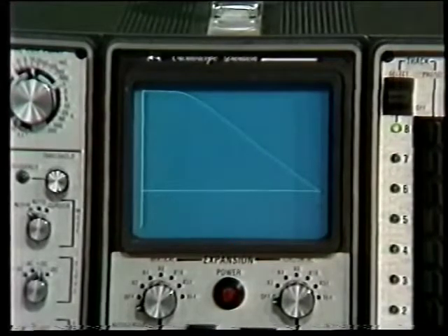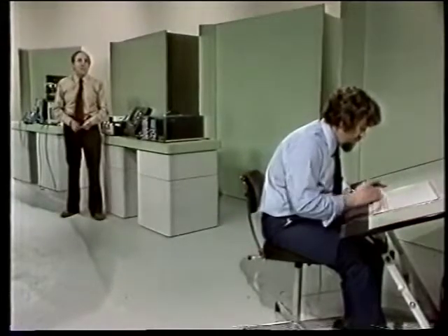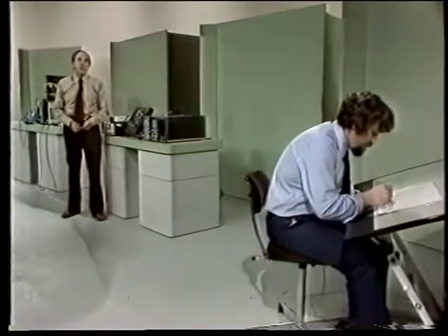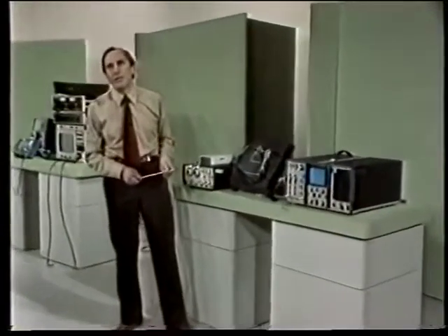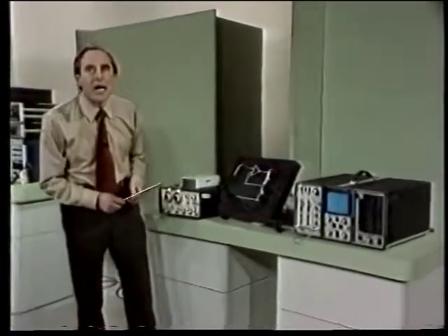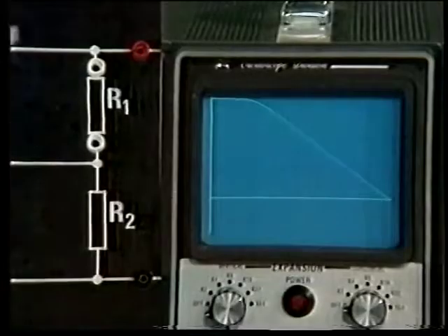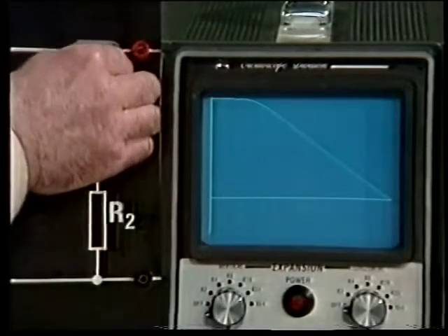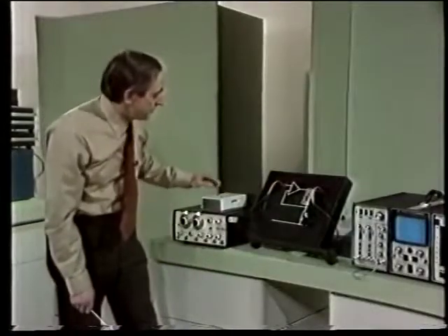I can read the important values of gain and frequency off the display, and I'll ask Nick Heap to sketch and label each curve as it is traced out. But since the system takes rather a long time to trace out each curve, I'll start the next one before asking Nick to sketch the first. This time, I'll close the loop by plugging in R1, which I've chosen to be 99 kilo ohm. Now I'll start the sweep again.